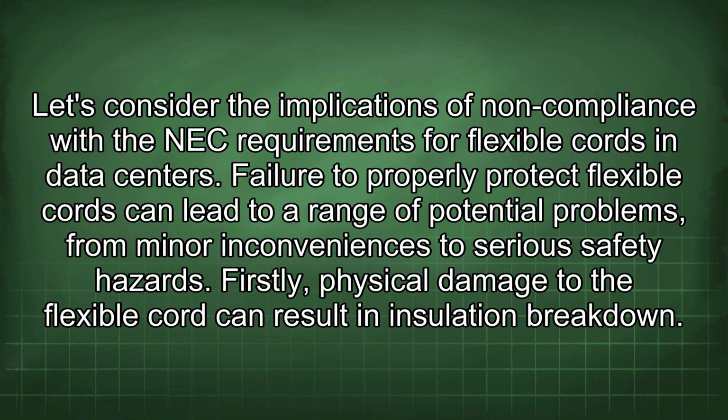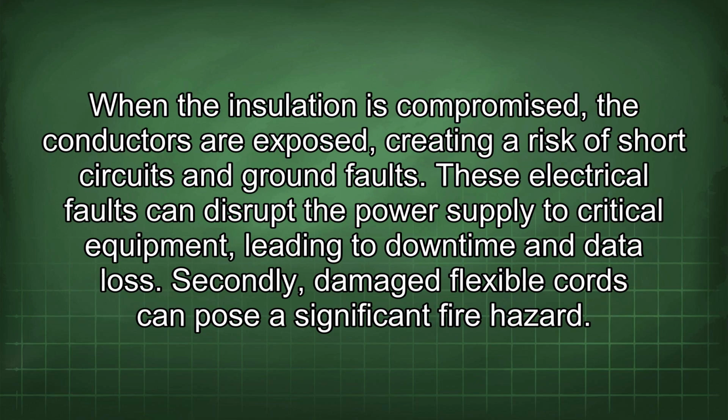Let's consider the implications of non-compliance with the NEC requirements for flexible cords in data centers. Failure to properly protect flexible cords can lead to a range of potential problems, from minor inconveniences to serious safety hazards. Firstly, physical damage to the flexible cord can result in insulation breakdown. When the insulation is compromised, the conductors are exposed, creating a risk of short circuits and ground faults. These electrical faults can disrupt the power supply to critical equipment, leading to downtime and data loss.